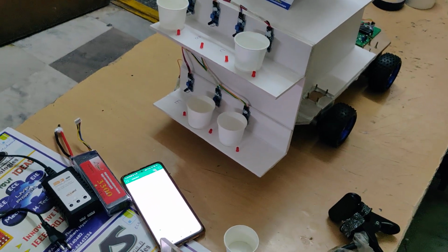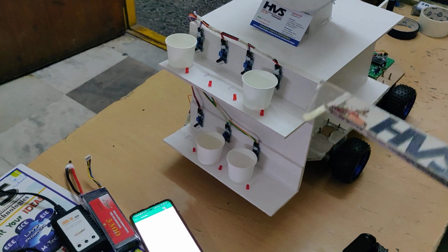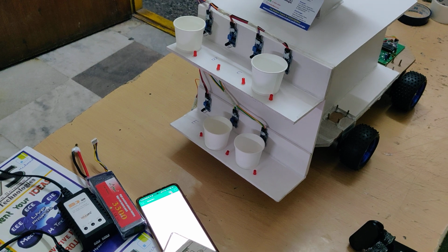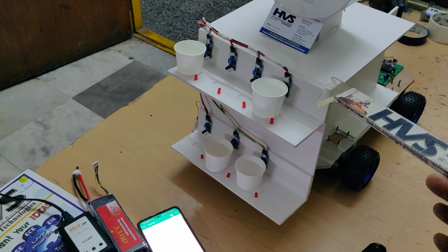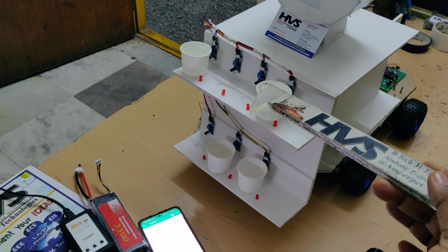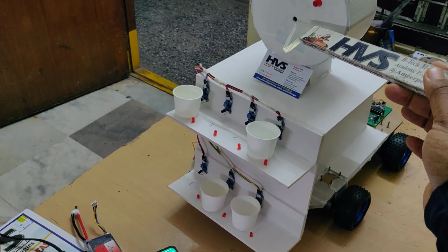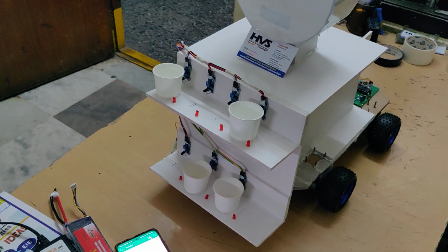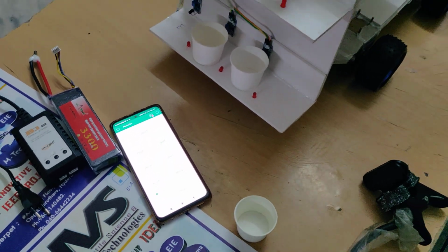From the Blynk application, we can set the bed number and the robot will start moving. Once it reaches the bed number, it will inform the Blynk application that it has reached the particular bed number, and will announce through the voice circuit to take the medicine, and that will be identified by the IR sensor. Once the medicine has been successfully delivered, meaning it was taken, it will capture an image from the Pi camera and send message alerts including email alerts, and after that it will go back to the junction again, right? So let us see the demonstration.